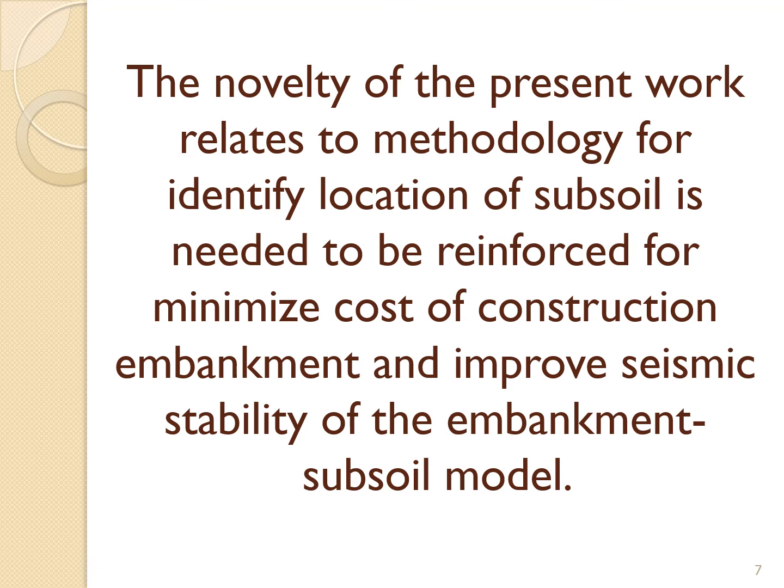And when the geogrid sheet distance is less and the geogrid elements are used with a small distance, of course the displacement is reduced and we will have less displacement, but economic design of the geostructure is very important.